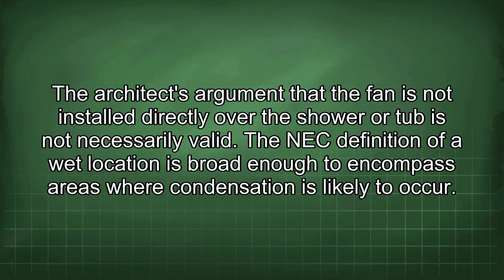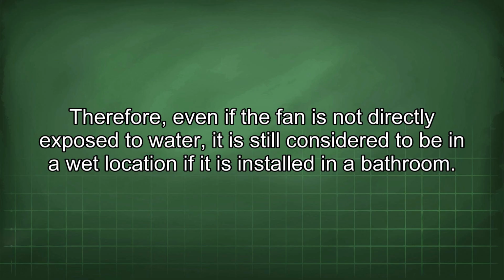The architect's argument that the fan is not installed directly over the shower or tub is not necessarily valid. The NEC definition of a wet location is broad enough to encompass areas where condensation is likely to occur. Therefore, even if the fan is not directly exposed to water, it is still considered to be in a wet location if it is installed in a bathroom.